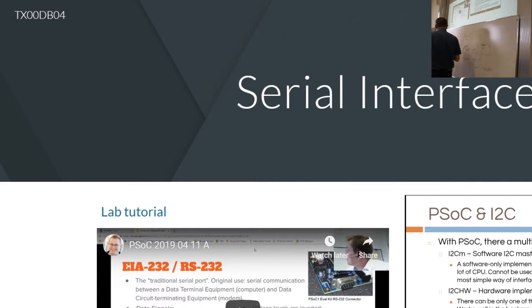Okay, but anyways, there was also that 4.7K pull-up resistor here. Actually, this usually works also without that one, but just in case. It's actually in the PSoC documentation to add that external resistor there.